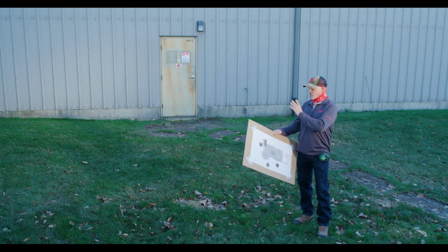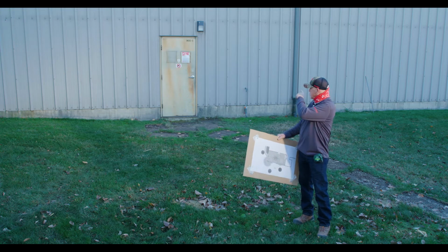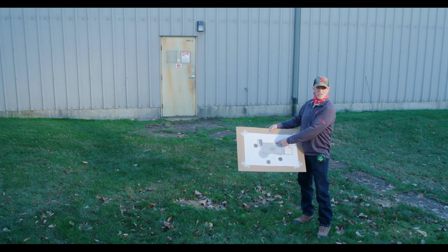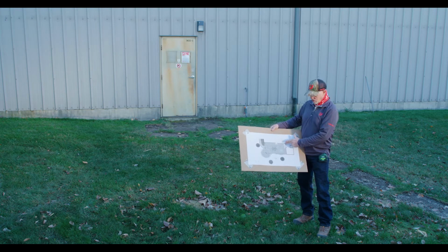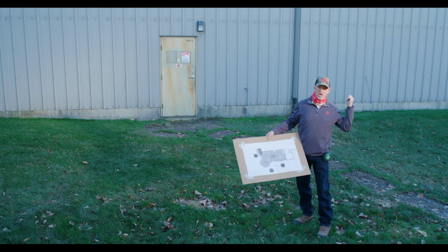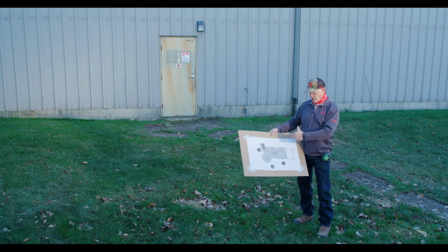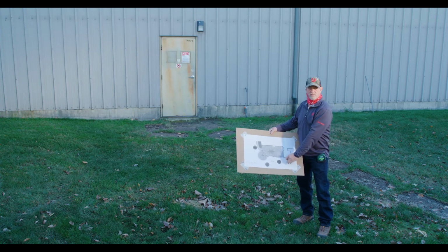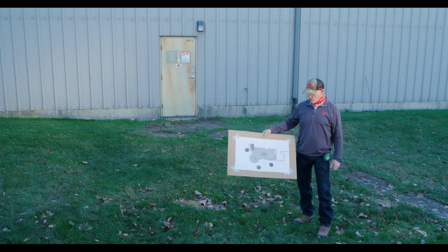Now we're going to use that back wall and specifically that service door as our benchmark, as our starting point on this layout. We're also going to establish this perpendicular side. Obviously we don't have that in real world, but here we're going to lay out a 3-4-5 perpendicular line to be able to achieve that point of reference too.